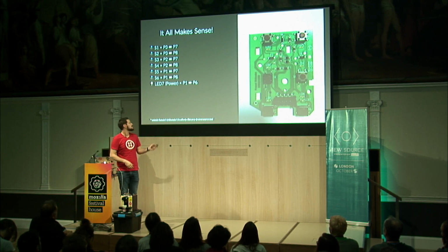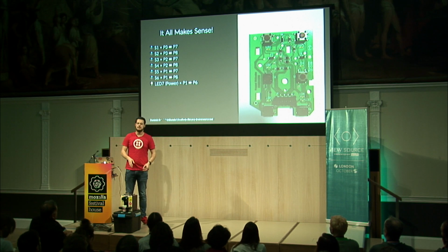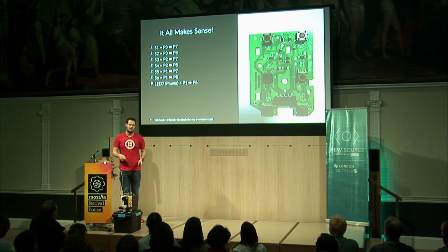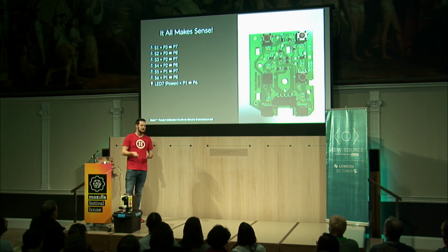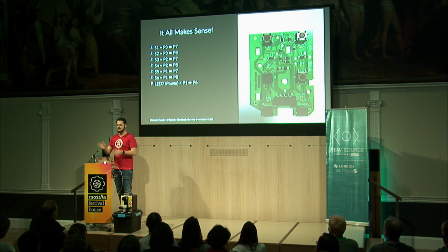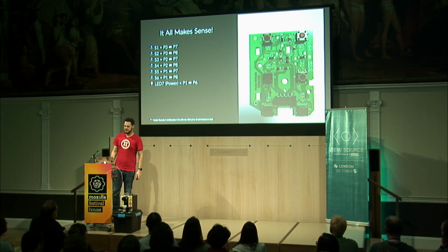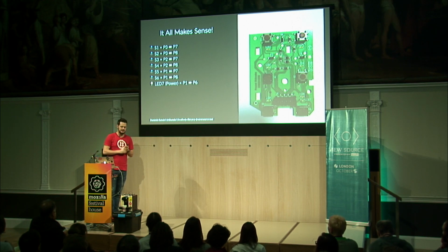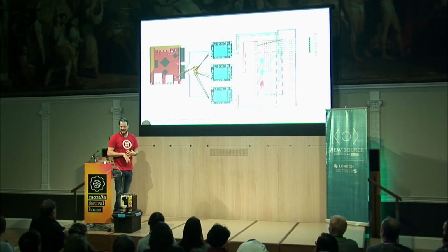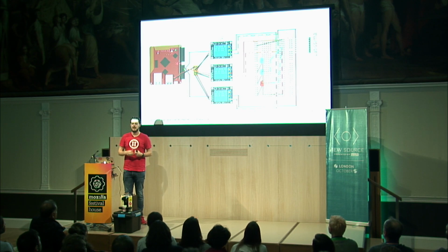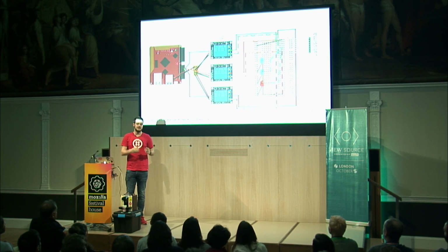Basically, it was mappings between the different power pins and the switches. That, however, also meant that making this a digital protocol isn't really convenient, because we would need to be on the same rhythm that the coffee machine has. But luckily, my flatmate was smart enough to say before, hey, we should probably look at this thing called relays. If you don't know what relays are, basically they're a way for you to have a switch that you can digitally control.